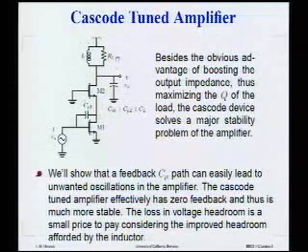In other words, if I remember when we calculate the quality factor of this tank, it's all the resistors that appear in parallel at the output. So RL appears at the output, right? And the R out of this device appears at the output. But because this is a cascode device, its R out is actually much larger, larger by this degeneration of this device. So that means I can get a higher Q at the output.